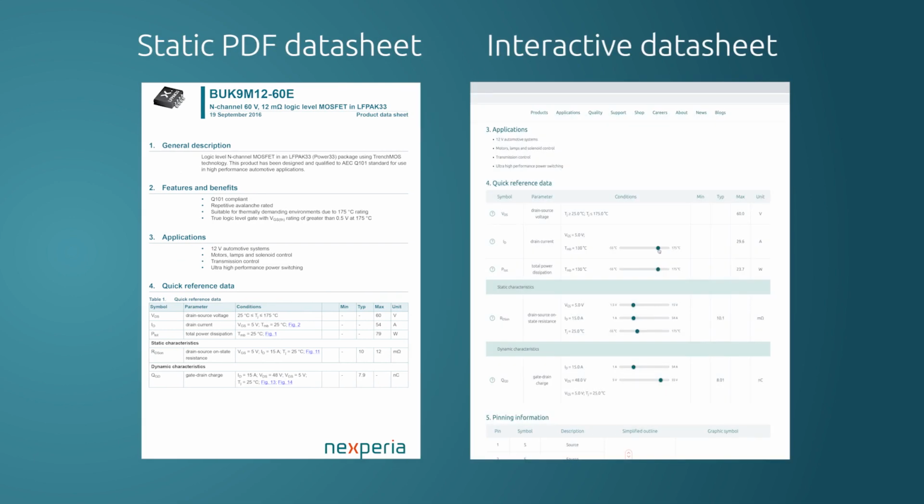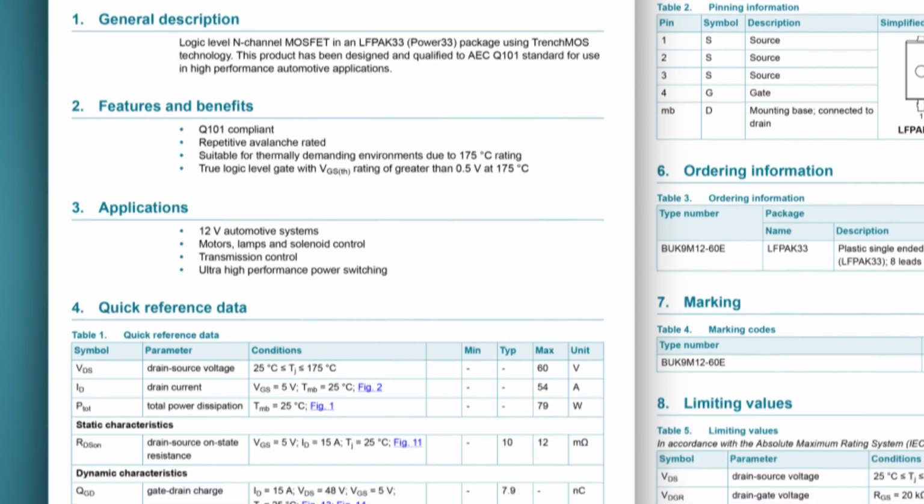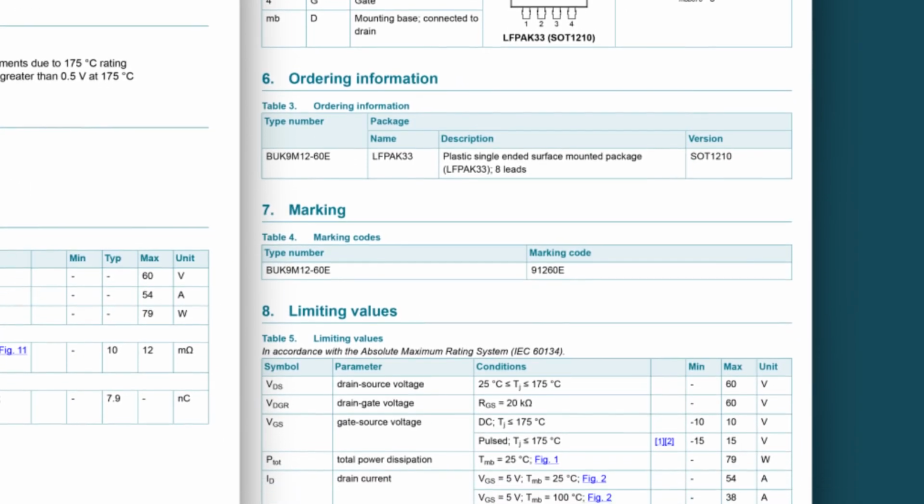Now, the static version is based on a curated set of data from measurements, from characterization, from product line testing, and from those different samples of data, we then do some statistical work, and we then also add in all the different margins. And with all that in mind, then we create a static datasheet. The goal of the static datasheet is to create a guaranteed specification for where our manufactured devices are going to fall within the static datasheet.